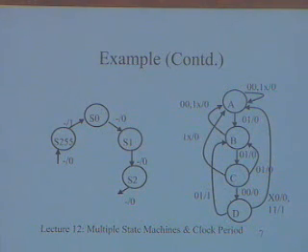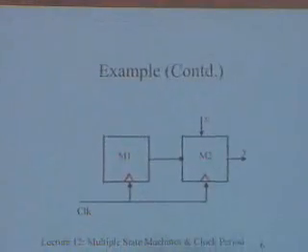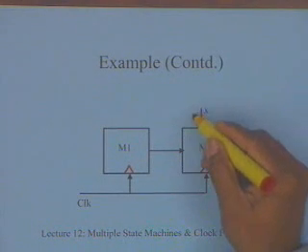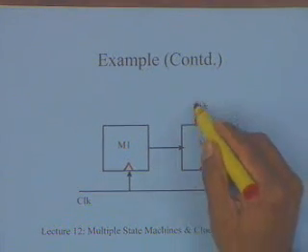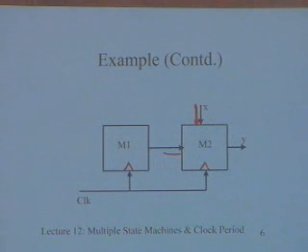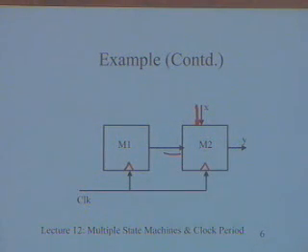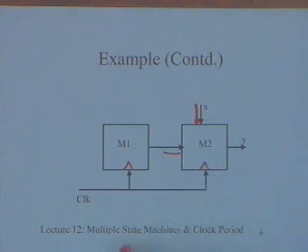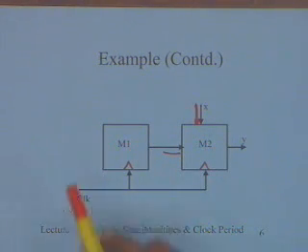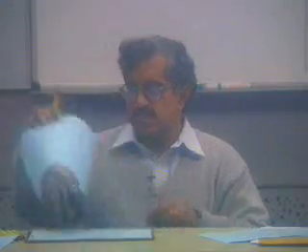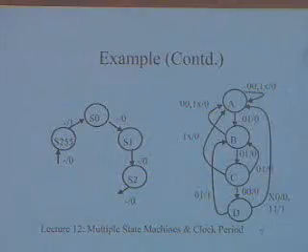The second input: if you consider M2, it now has two inputs, one coming from the external input and another coming from M1. The role of this input is primarily initialization. It should be able to initialize this state machine back, because the block boundary is going to begin, so I should come back. This does create some complications in the state diagram that you need to realize.